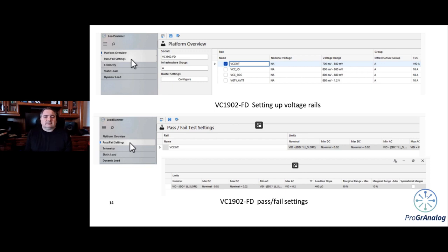So that's where you essentially develop your test vectors for your testing of this device. And you also set the margin. You're going to see the margin in a few more slides. You'll see the marginality, right? A lot of feedback has been, okay, that's cool, it's a pass, it's a fail, but where does it get close to a fail? Because that's where we want to hone in, and see what that is, because quite often that's going to allude to a problem, like a time constant problem, that marginality. So the marginality is also configurable through this input stage.